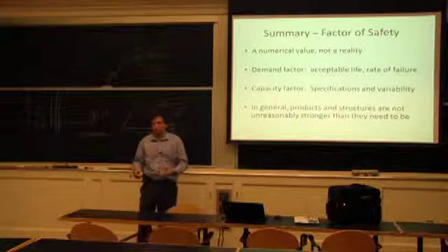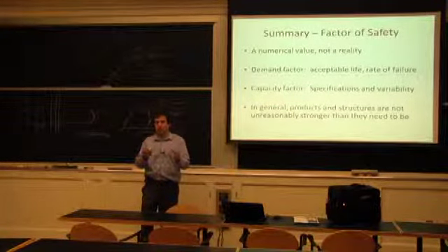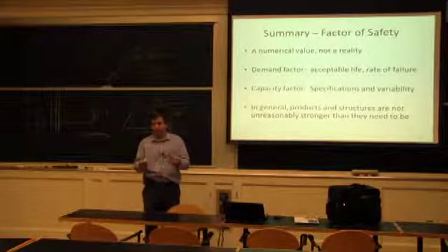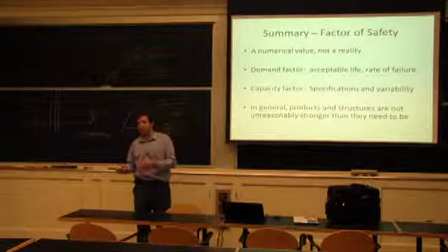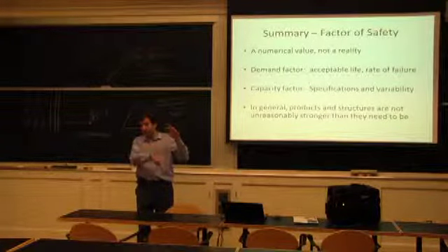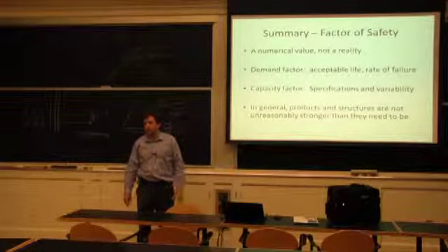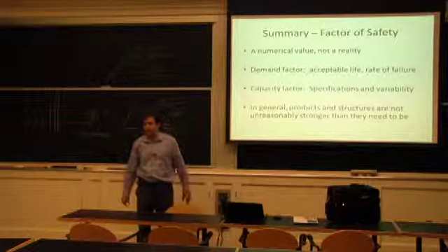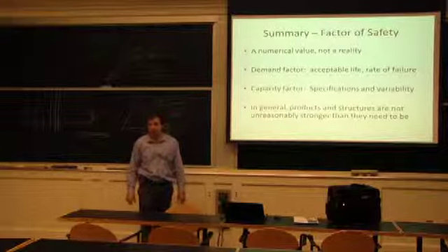And that's fine. What's actually important is to be consistent. So if you're making the design of a car in a certain way, and your history tells you it's strong enough, you can keep doing it this way, because you have your built-in history. You may be able to optimize it gradually, but you have to keep watching to see that you're not getting beyond what's acceptable in service. If you're relying on the service history a lot, you have to keep track of it in a more detailed way. Any questions? Any comments?